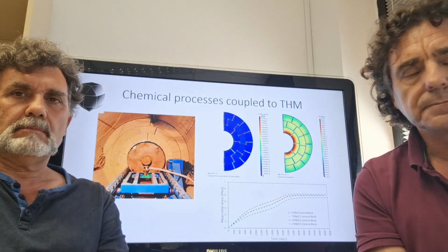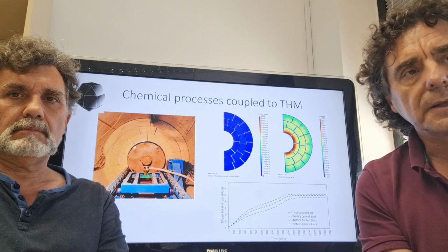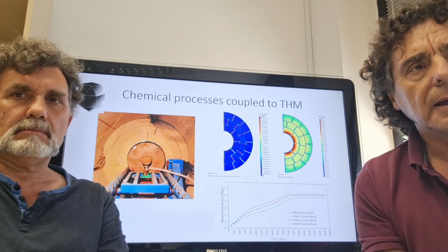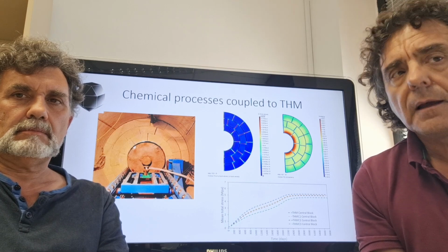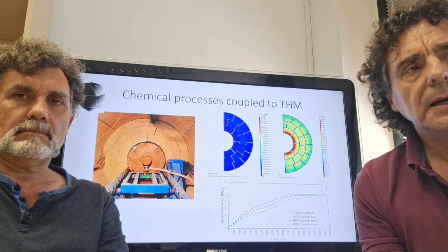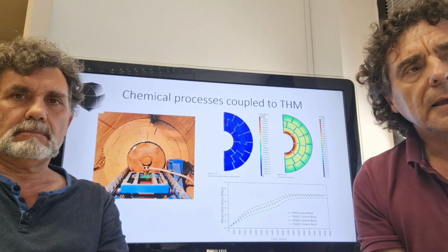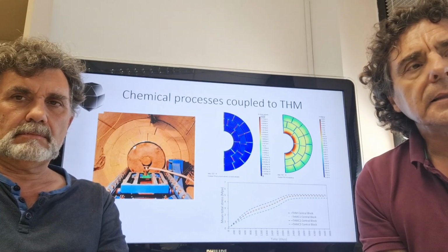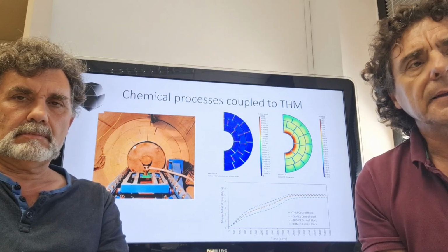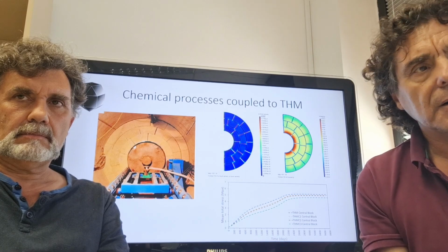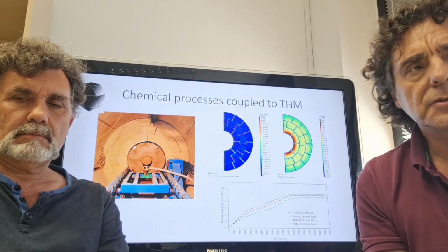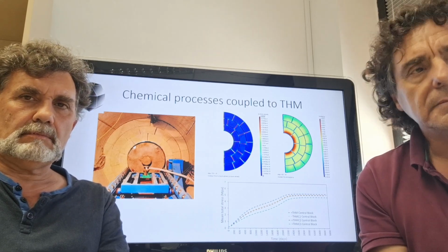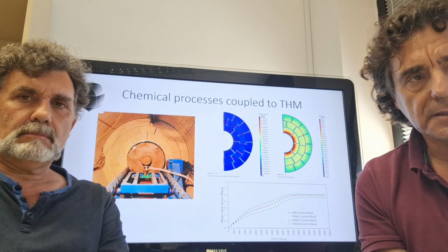Another direction of research is related with the chemistry. Chemistry is a process that we have to incorporate to the thermo-hydromechanical equations and has influence on many of the applications that we are working on. For instance, in this slide I summarize the effect of salinity on the swelling behavior of clay barriers: when the ionic strength changes due to the presence of salts in the solution, that affects the swelling of this material and can reduce it, and then it has an influence and has to be investigated.